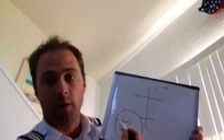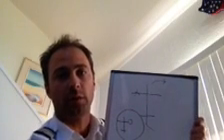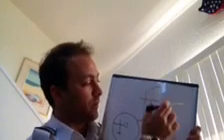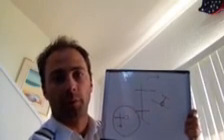So you're having a greater flow of air over the outside wing as opposed to the inside wing. In this situation where the aircraft is being yawed to the right, this wing here is creating more lift simply because it's traveling through the relative wind faster, and it's going to cause the aircraft to roll to the direction of the turn that we've input through the rudder.